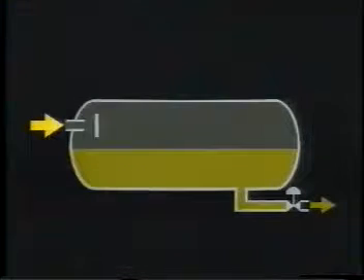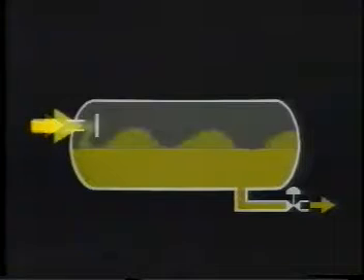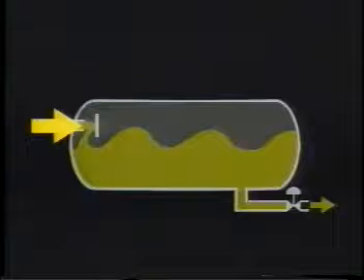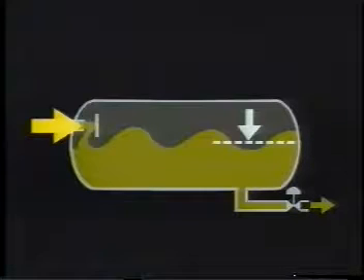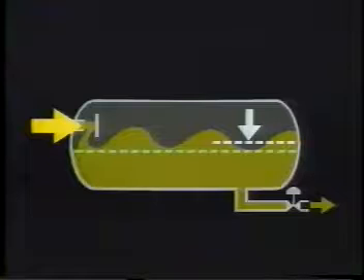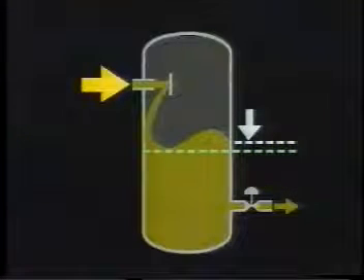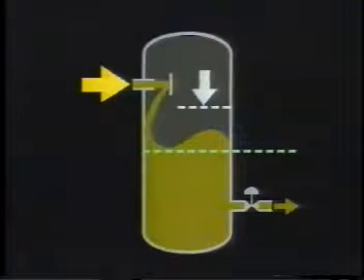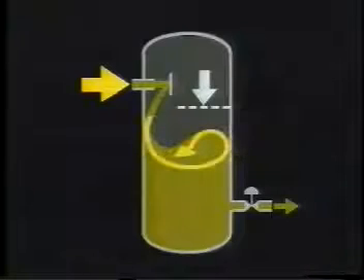Additionally, horizontal vessels have less liquid surge capacity. That is, they handle large slugs of liquid less efficiently than vertical separators. The geometry of a horizontal vessel requires any high liquid level shutdown device to be located close to the normal operating level. In a vertical separator, the shutdown could be placed much higher, allowing the level controller and dump valve more time to react to the surge.